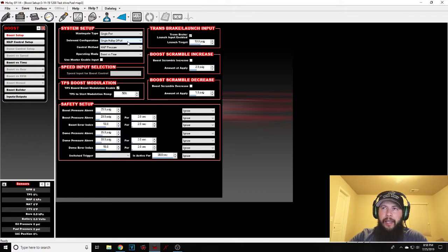And it really depends. I like using a 4-port because we occasionally do some stuff on some really slick surfaces, so I need to be able to turn the power way down. I want to be able to go down to 4 psi, maybe even a little bit lower, but I also want to be able to max out my turbo setup. So that's asking more than a 3-port solenoid can provide. A 4-port solenoid is going to be taking the pressure away from the bottom of the gate, which would be aiding the spring to open that gate, and adding it to the top of the gate. So 100% will be everything to the top of the gate.